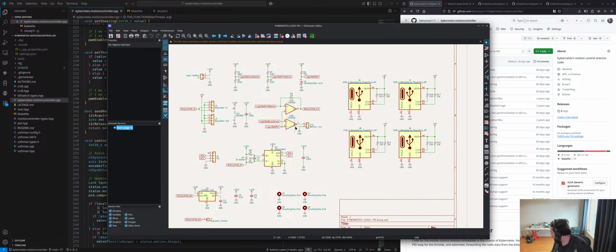So I very much tend to try to build out-of-band kill switch systems. On any robot that can outrun me, I designed the remote kill switch such that everything else on the robot could have failed, and I can still turn it off, just from a protect-your-investment perspective.